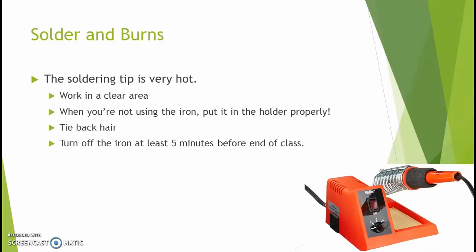When you're not using the iron, it needs to go into the holder properly. This is absolutely critical. So the holder is designed to make the extremely hot tip of the soldering iron inaccessible to skin. So go ahead and put it back in the holder as is shown here. Don't forget to tie back your hair. Nobody enjoys the smell of burning hair in the classroom.